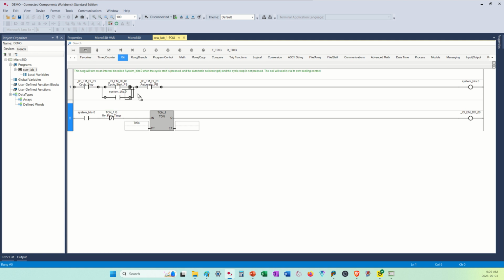I'm going to have to play some fancy pants here. I'm going to change this from a regular contact to a latch. Now I can go up to the top and hit set reset, or since that's highlighted, I can press my space bar. That's now a reverse coil. If I left it alone that way, then while the timer was not finished, it would be true, when it's finished it would be off.